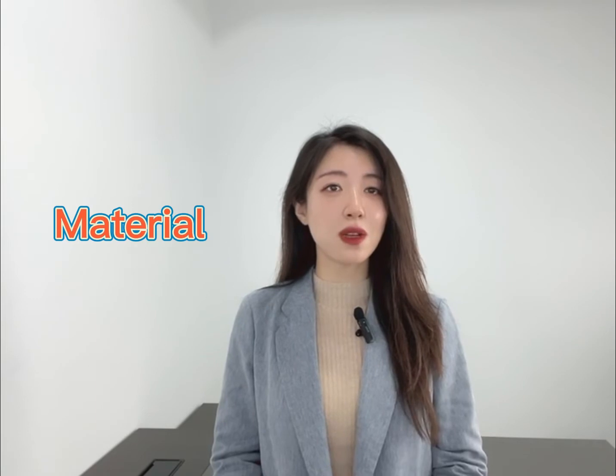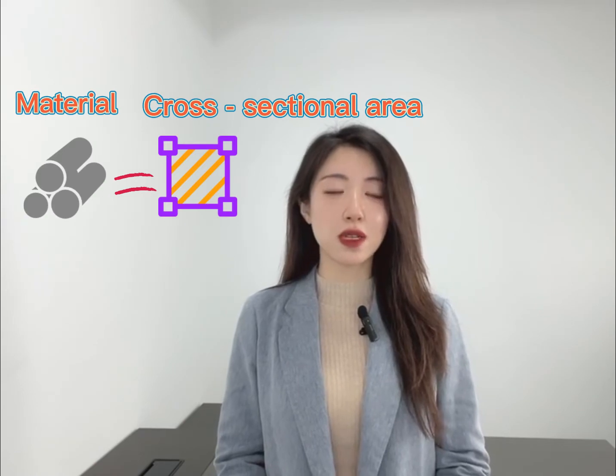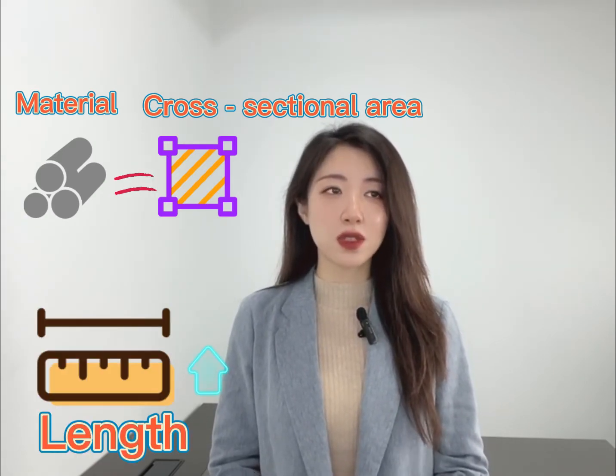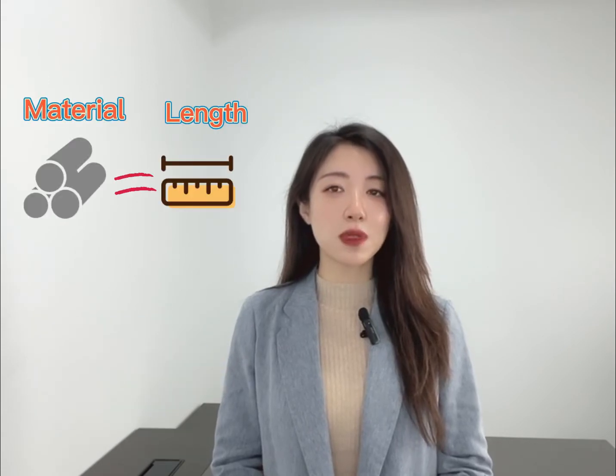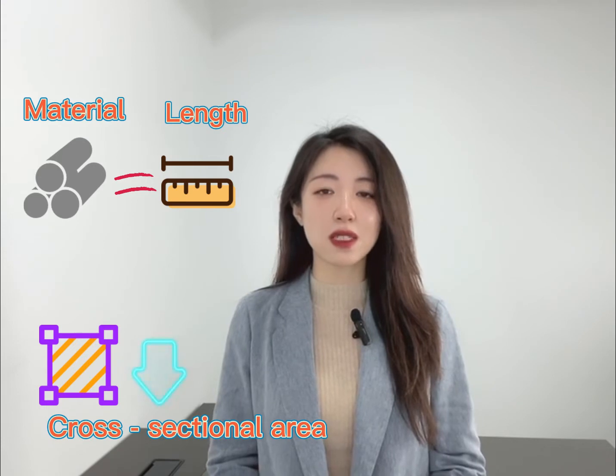The factors affecting the resistance are the material, length, cross-section area, and temperature of the conductor. When the material and cross-sectional area are the same, the longer the conductor length, the greater the resistance. When the material and length are the same, the smaller the cross-sectional area of the conductor, the greater the resistance. When the length and the cross-section area are the same, the conductor resistance of different materials are different.